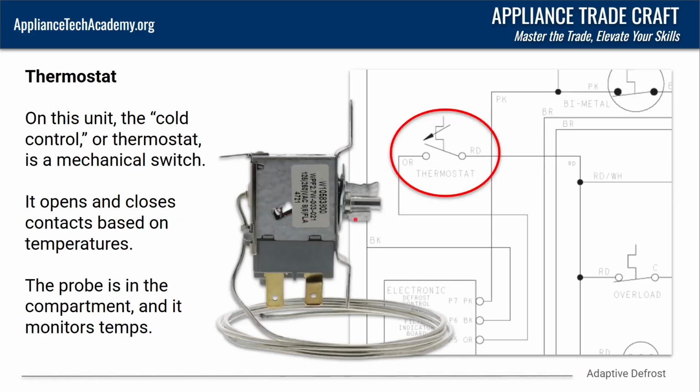Now, let's look at the thermostat real quick before we dive in deeper. On this unit, the cold control or the thermostat is a mechanical switch. It opens and closes the contacts inside, and you can see just two wires going in. Same thing on our diagram right here. We'd have an orange wire coming in, red wire going out. It basically opens and closes contacts based on the temperature.